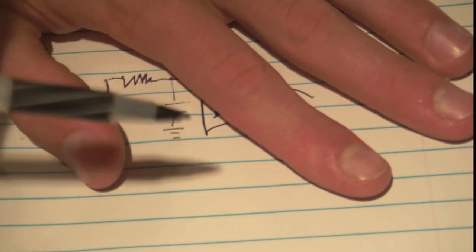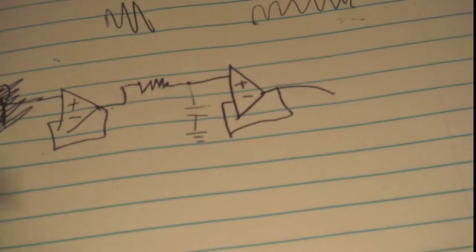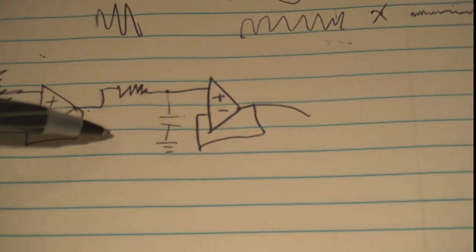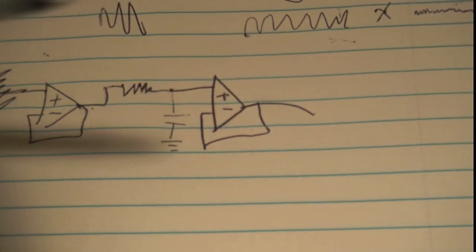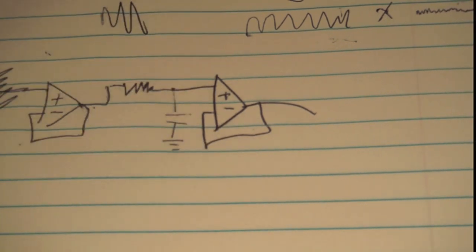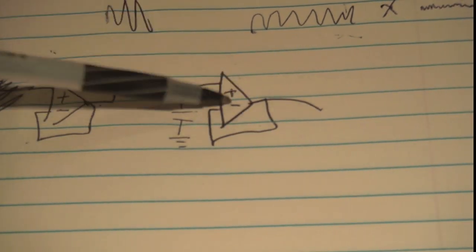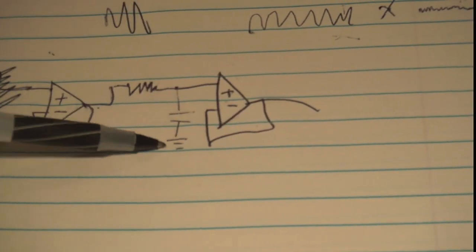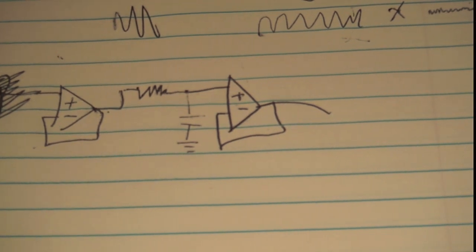But any loads on the output, where you're going to want to drive something, are going to influence the filter because of extra resistances, capacitances, and inductances, etc. So you're going to want to buffer the output. This means that you have the op-amp driving the circuit, not the filter, so your cutoff frequency is going to remain the same. So this is sort of a basic design.